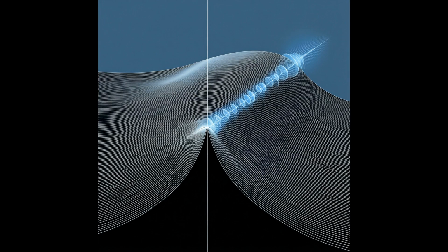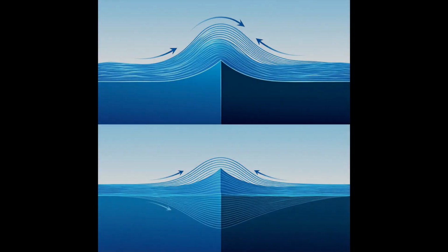Lower frequency signals have longer wavelengths, allowing them to diffract more effectively around large structures like walls. In contrast, higher frequency waves with shorter wavelengths tend to shadow behind obstacles rather than bend around them. This geometric behavior explains why your router's 2.4 GHz band often reaches rooms better than the 5 GHz band despite similar power output.